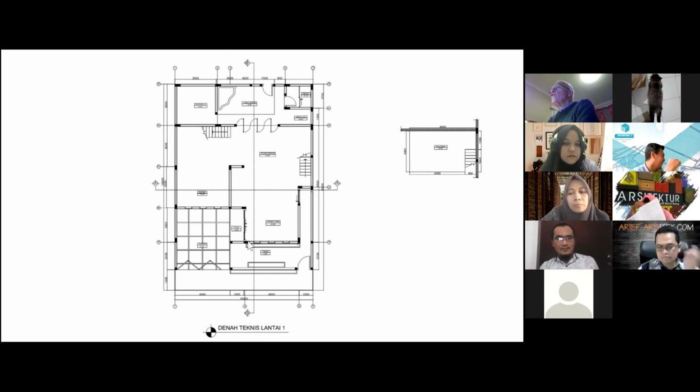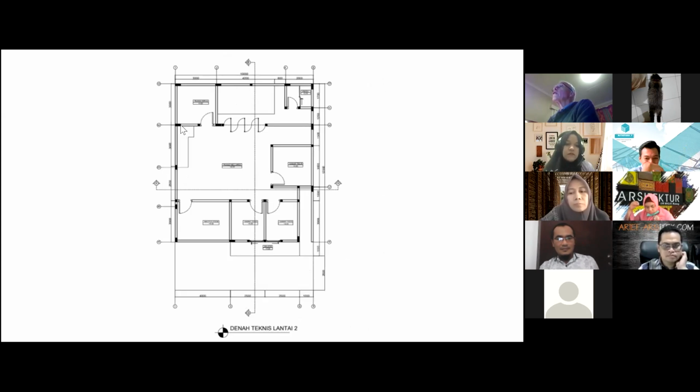And do they go up to the roof? Let's check. Well, yes, this wall goes up to the roof, although it does have an opening, a door, which will weaken it. But this wall here is very good because it has no penetrations and it goes right up to the roof. So we do have some resistance on line E from these two, which could be confined masonry walls. So that's good. We've got some resistance at last.